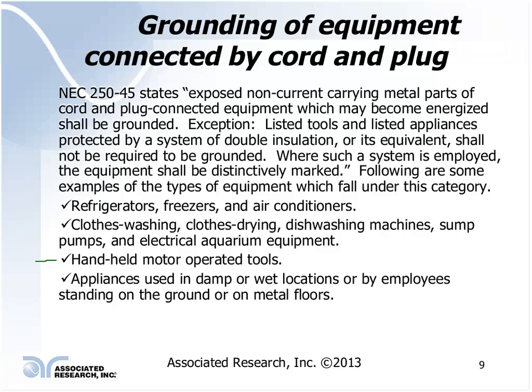If you're holding on to a product, you've got a pretty good grasp on that, and if that insulation should fail, the odds are pretty decent that you're going to receive an electrical shock unless you have that second level of protection, either the ground system itself or the system of double insulation.